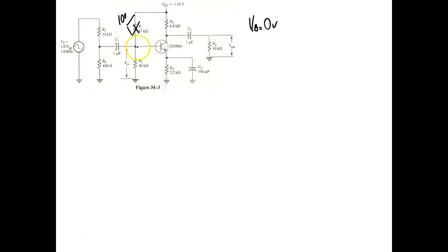But what's going to happen? My input's 1 volt, so it's going to exceed 7/10 of a volt. Now the transistor's going to turn on, but it's going to give me these little pulses up there. So we're going to lose the whole positive alternation on the output. This voltage right here is going to go to, what's it going to go to? It's going to go to 0 when I measure it with my meter, right? The transistor is going to move toward cutoff, and this guy here is going to go way up. So first of all, let's open the capacitor and see what's happening.